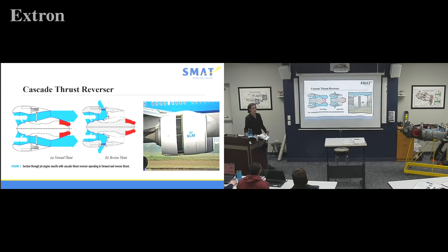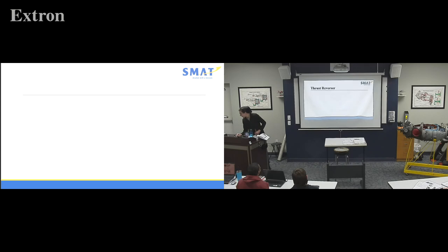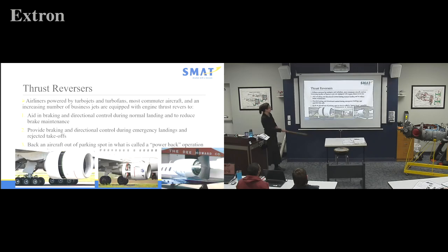Isaac sent us a picture of the previous slide. So this one is just coming out the very back of the engine. Oh yeah, there was this at the bottom. Yes, the 319, in the middle. Yep. So I would think this is somewhat of a combination, although it's in the side, it's not coming out the back. So there's cascade vanes inside. So rather than sliding back the cowl, they're just opening up sections. Thanks, Isaac.